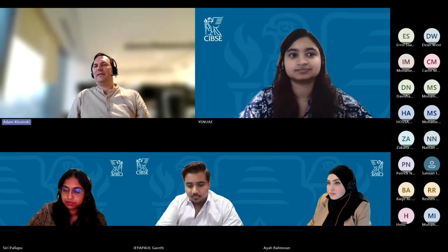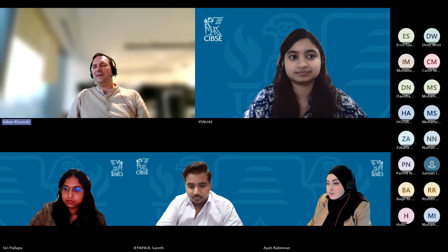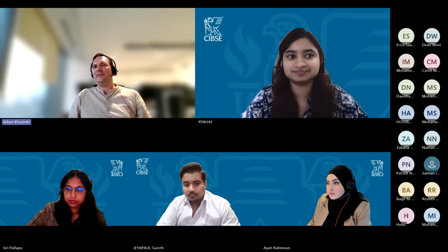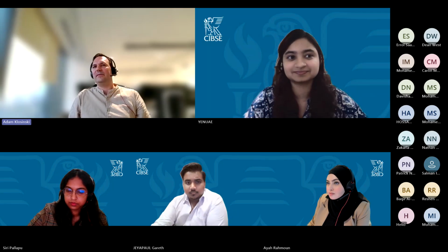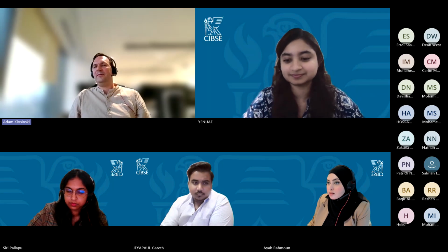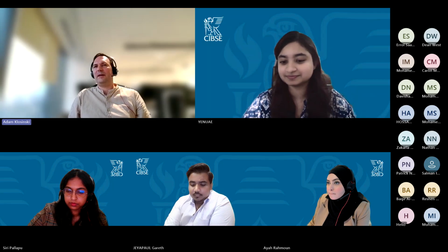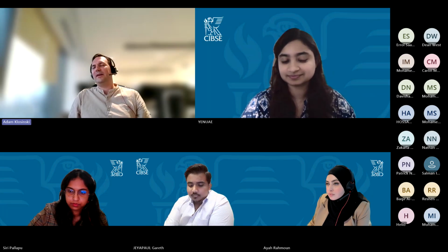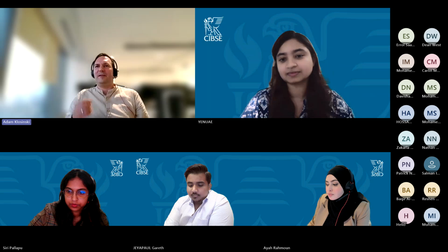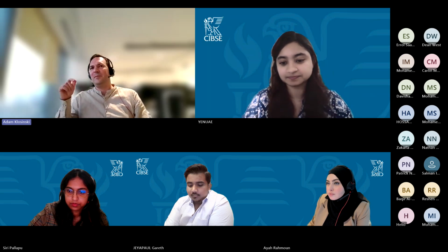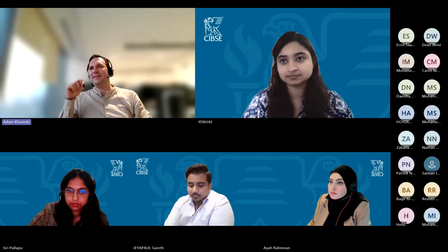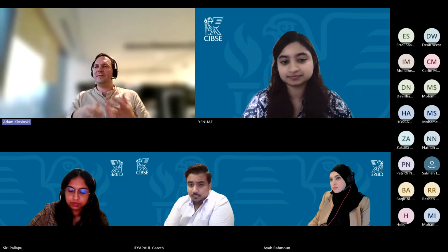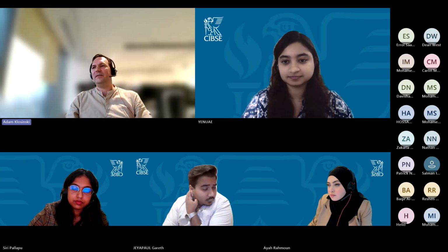But once again, once everything has been done automatically, we always need to check how it's been done. Even if we provide the initial parameters, for example, always do the clash resolution going down, what if the space above is available in this case? So you always need to get into the details, in fact.